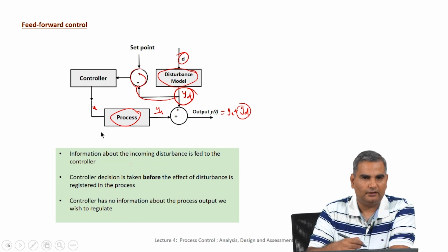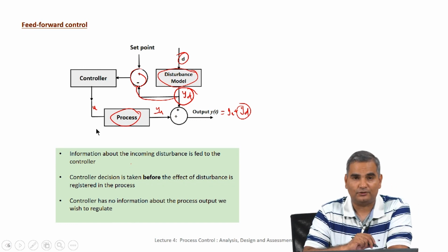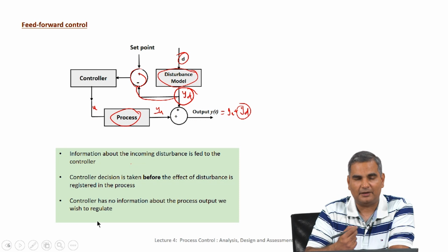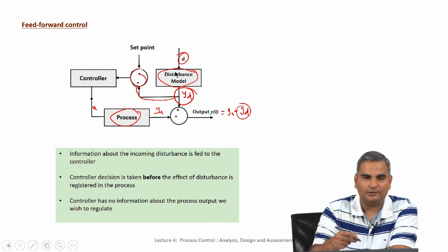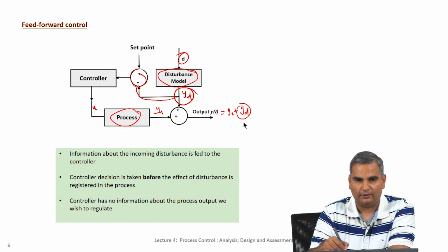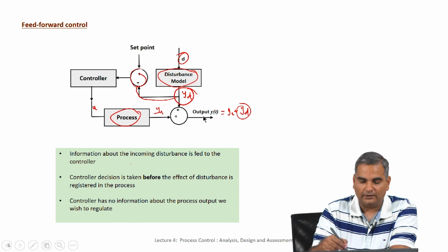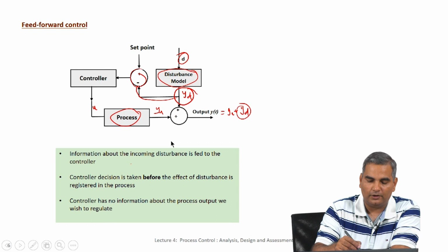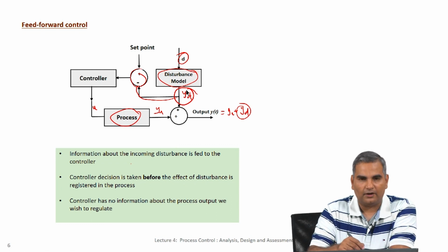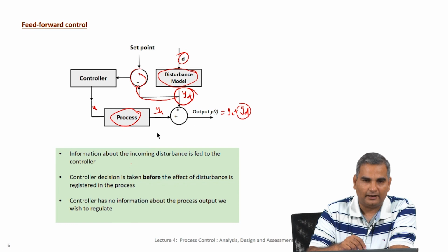Okay. And of course, in more sophisticated systems you could actually integrate both feed forward and feedback controllers together, and then you could have an integrated feed forward feedback controller, which, if you have the disturbance measurements and so on, will be very effective. And you can imagine why, because since you are anticipating the changes that are going to occur in y d based on the disturbance measurement, you can automatically change u, and whatever does not get fixed by the feed forward controller because of either poor measurements of disturbance or poor models, those can be fixed by the feedback error based control.